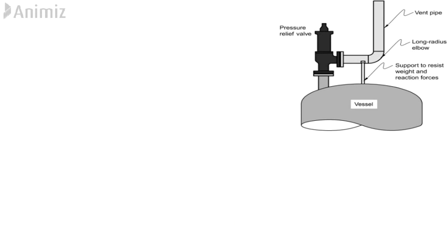Which by simple meaning is that the set pressure of relieving devices should always be less than the maximum allowable working pressure by at least 10%, considering the safer side of the vessel and relieving devices.